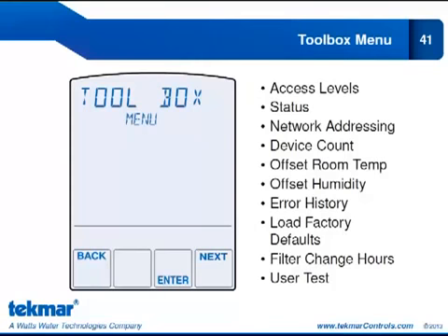I can see in the status if the thermostat is in normal operation, if it's overriding the radiant floor because of the radiant floor warm weather shutdown, if we're in floor cooling, if I'm in warm weather shutdown or cold weather shutdown, if I've hit a floor min or floor max, if it's in an interlock wait time between heating and cooling, that will appear at the status item. And if my hydronic heat is off, that will also appear at the status.